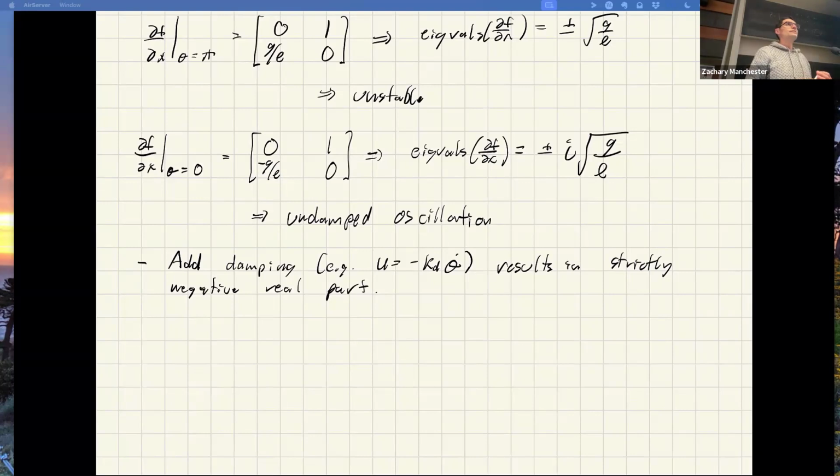I mean, this whole eigenvalue concept is really based on the fact that near an equilibrium point, x dot equals 0, and I can locally approximate the dynamics there by A times x. If you're not at an equilibrium point, that f of x doesn't equal 0. So this doesn't hold up, right?